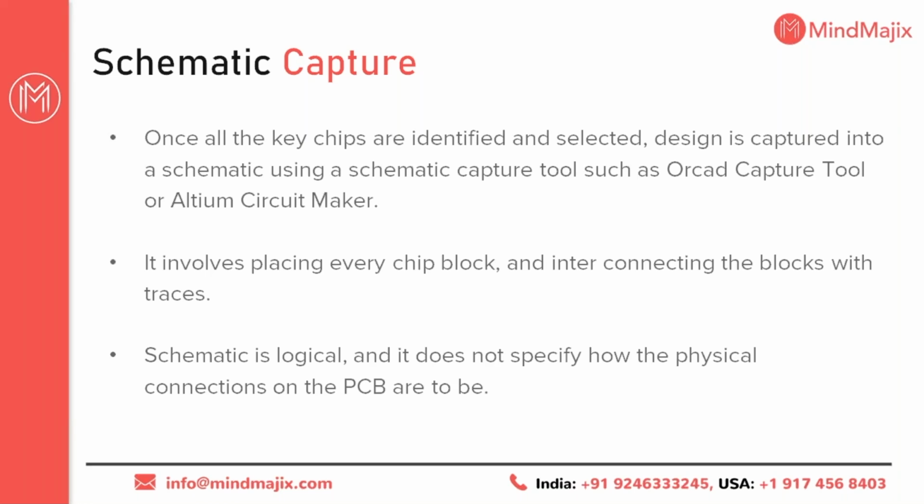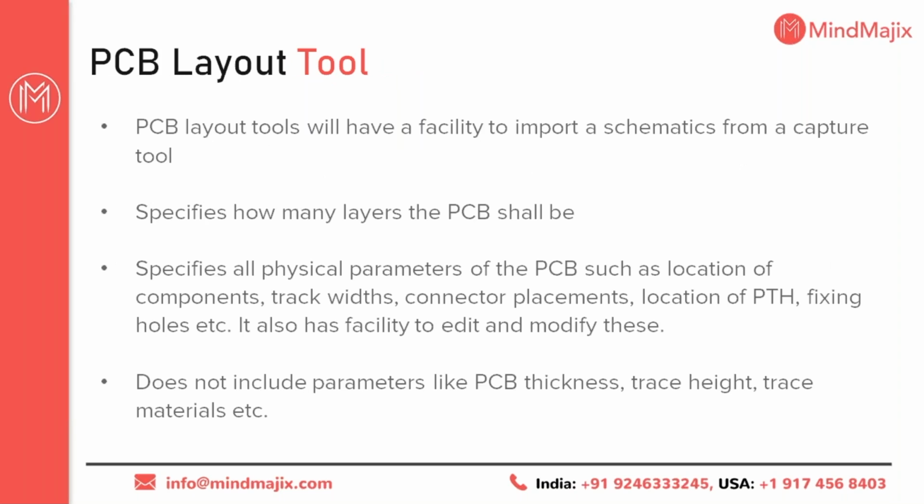Schematic is logical. It does not specify how the physical connections on the PCB are. It does not show where exactly on the PCB the connection is going to reside. That is typically done in the PCB layout tool, and the PCB layout tool has a facility to import the schematics. The schematics that are created during the design process are imported into the layout tool, where you specify how many layers of the PCB you are making and import all the connections into the PCB layout tool.